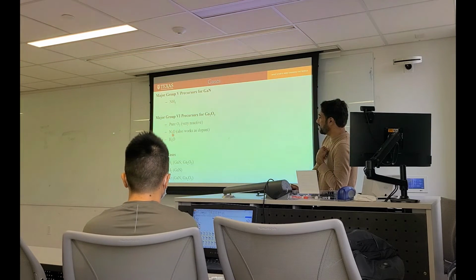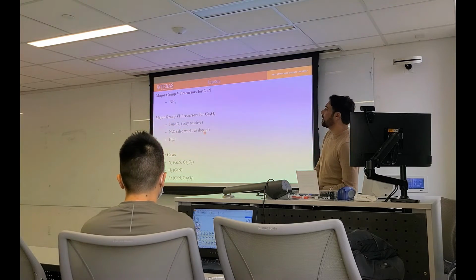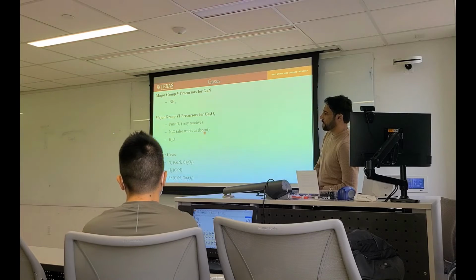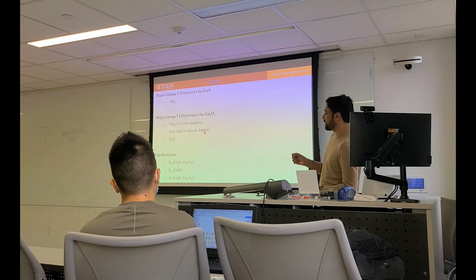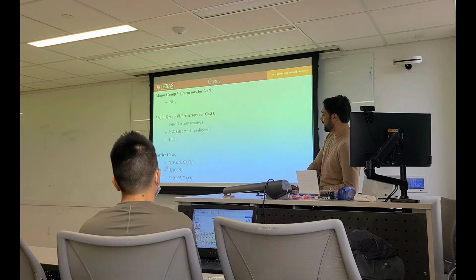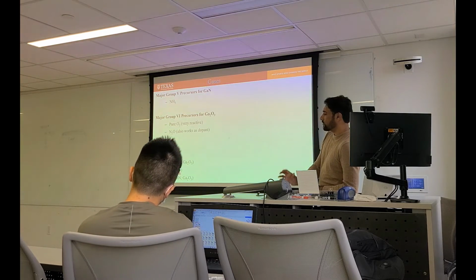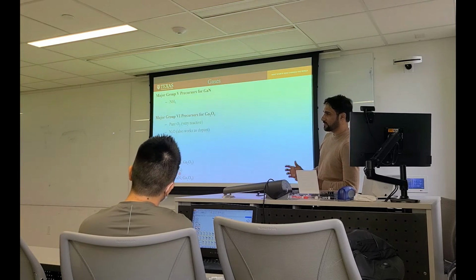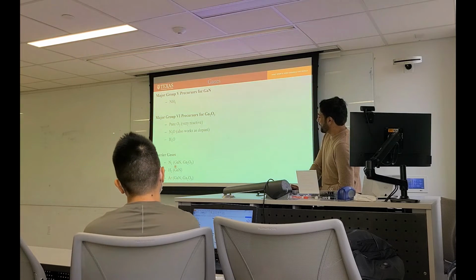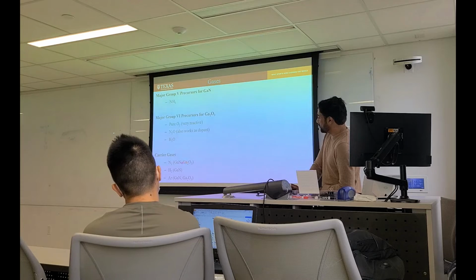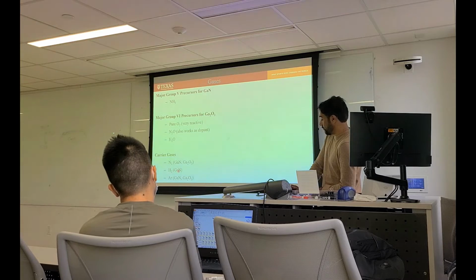N2O, recently a few research groups have used N2O. It is also used as a dopant. It is a really good precursor because it does not fully break in the vapor phase, so you can have very nice morphology on the substrate. Carrier gases, as I mentioned before, are N2, H2, and argon. H2 can never be used for gallium oxide because it reacts with oxygen and anything can happen. So only N2 is used for gallium nitride and gallium oxide. Argon is used for gallium nitride and gallium oxide. H2 cannot be used.